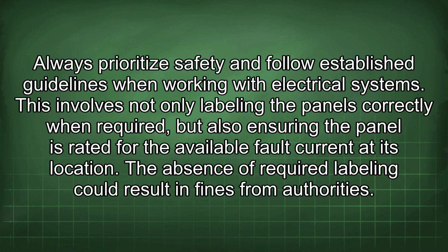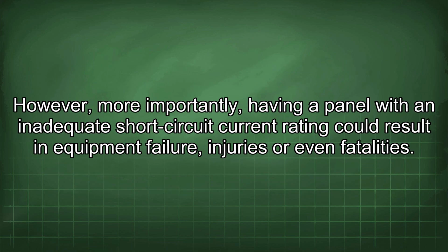This involves not only labeling the panels correctly when required, but also ensuring the panel is rated for the available fault current at its location. The absence of required labeling could result in fines from authorities. However, more importantly, having a panel with an inadequate short-circuit current rating could result in equipment failure, injuries, or even fatalities.